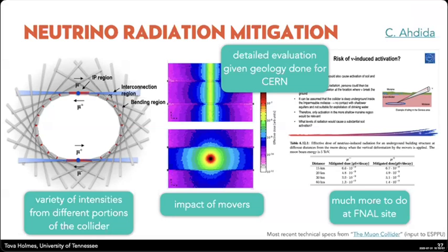Yeah, so just maybe synergies with fusion research and MRI. Sure. So for the fusion research, I mentioned the ITER solenoid. The ITER solenoid is lower field, I think 12 or 13 Tesla, but higher bore size compared to our capture magnet, in a way that in complexity very, very roughly balances out. So it's an equally challenging, similar kind of magnet. So definitely that experience will be really useful.